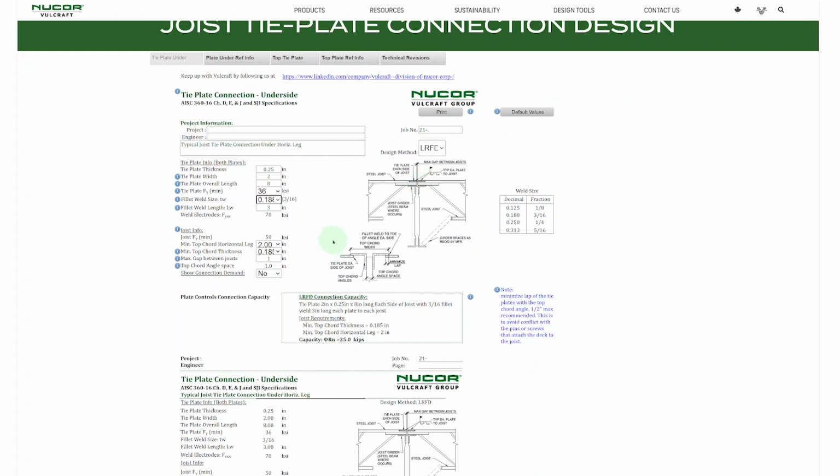So there's certainly a question of economy if that joist thickness wants to be that smaller size, but because of this connection it has to be thicker. That could potentially add weight to the joist design, which is going to add weight to the project and add cost to the project. So something to keep in mind as you're pulling the different levers of this tool trying to design your connection.